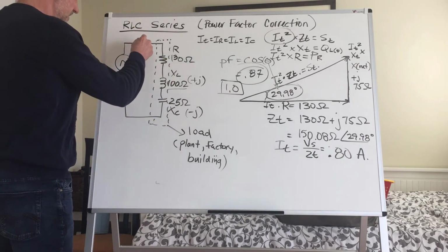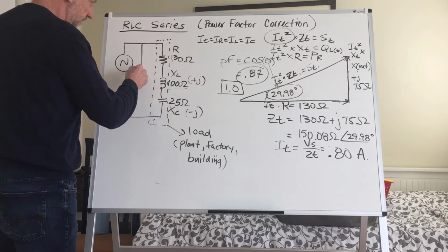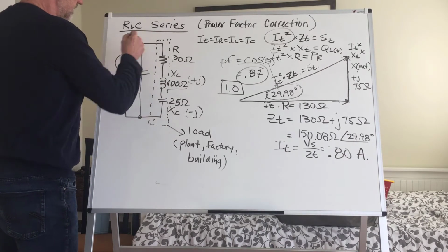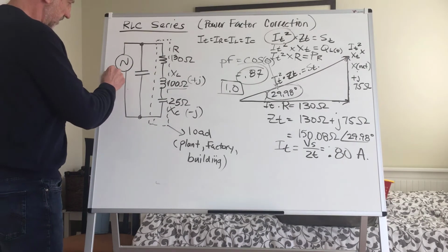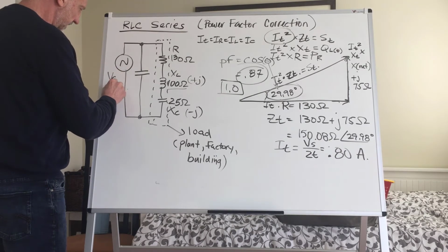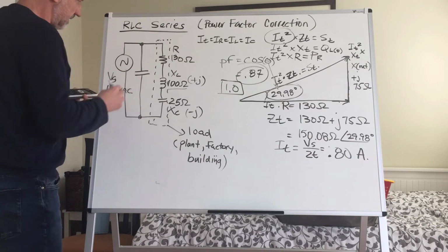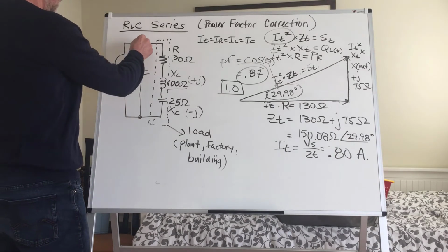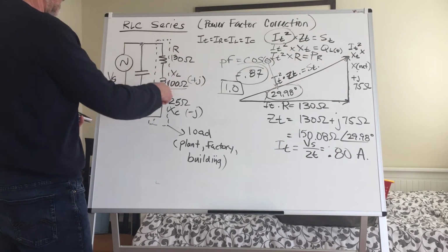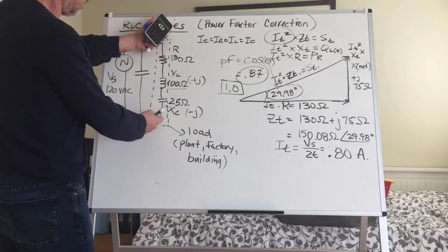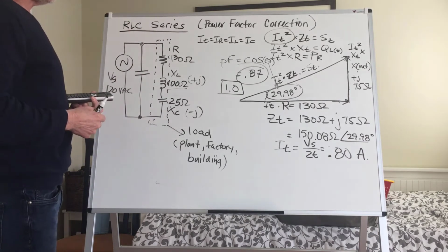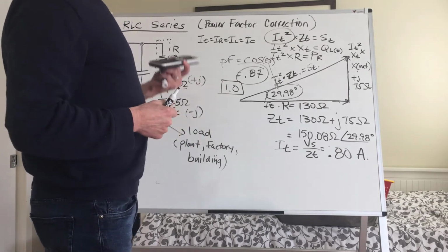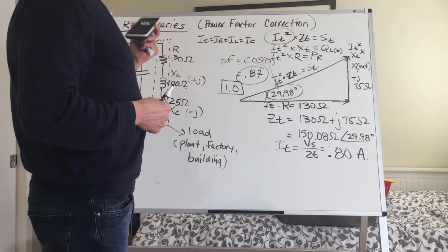And our correction always happens as a correction capacitor right across. Now remember, this was 120 volts VAC, right across the source. So this is where a correction capacitor goes every time, regardless of how the load's connected. Right across the source, right across the load to correct it and bring it to unity. So I'm going to pause it here, do some cleanup, and then we'll come back and approach this as power.